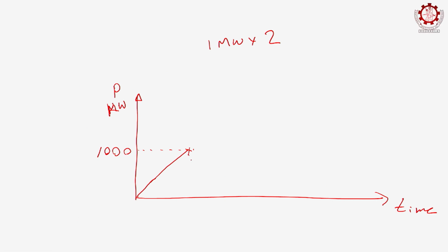What we will do is reduce this a little, to 75%, and then start the second machine. So, your total will then be increasing, because we reduced this one in order to start the second machine with a larger flow rather than starting with a small flow.